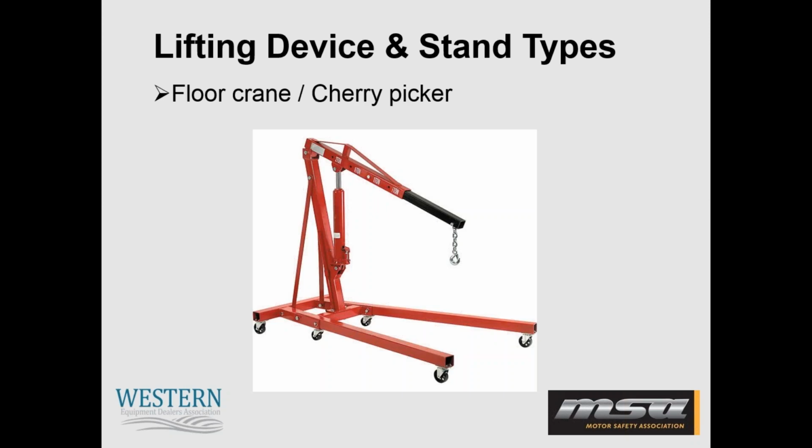We see these types of devices at shops fairly often, called a floor crane. I used to call it a cherry picker, but everyone may have a different type of name for it. And these two use a longer type of hydraulic bottle jack. But when you're utilizing these, just pay close attention to the outer tube. As your boom extends out of the tube, your capacity decreases. And the further your boom gets out of the tube, your capacity drops.